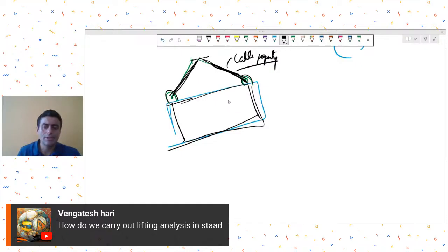Maybe in extreme cases, for very critical structures, maybe for this cable also you will have to look into the geometric non-linearity of this cable. That this cable may elongate, and due to that elongation, maybe some different type of forces get transferred to your main frame.